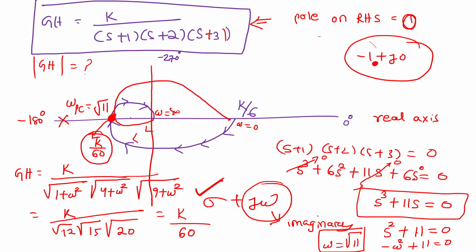If I put my -1 0 point at this point, see how many times it has a closed path. One closed path is this line. Two. So it will be 2. But what you want is 0, because the number of poles on the right hand side is 0. Yes, sir. So it means that definitely the critical point should be outside, right?